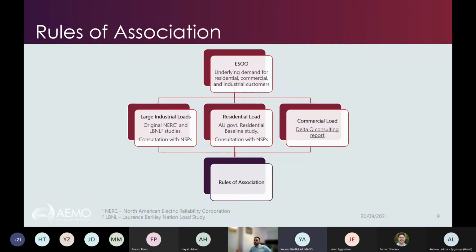Got another question. Shouldn't we take VSD-driven motors as VSD? It means the motor part doesn't take part anymore as a normal conventional motor. Yeah, exactly. So those power electronic loads that we've currently got modeled as VSDs, we'll take out of that power electronics load component and put in a separate VSD component. So it's not that we have VSDs modeled as motors here. We have them modeled as power electronic loads with a constant P and Q. Well, it's linear with voltage. But yeah, we're moving one step further, once those models get released by the WECC, to then have a separate VSD model. Thank you.